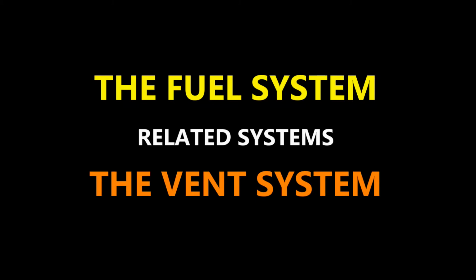Okay, so what comprises the entire tank venting system? Your venting system is going to involve your overpressure protectors and your vent protector. You have your valves, we're talking about your check valves and float valves. Okay, that's what makes it up. Now, there's a vent system for each tank. Each tank gets its own vent system. Each one has a vent pipe that's connected to its corresponding vent surge tank, and those are connected by a duct. Those are your stringer vent ducts.